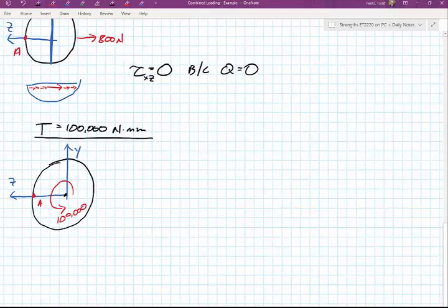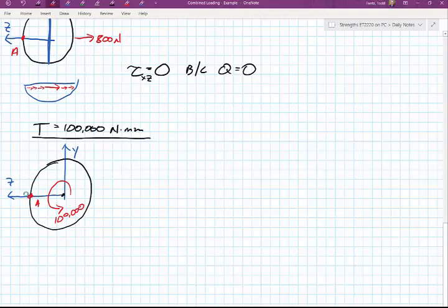So what would happen to my shear stress is, anytime you have a torque, it basically pinwheels around. The easy way to think of it, it's tangent to the surface. So this is my shearing stress. If I wanted to put a subscript on it, I'm still on the x face because the x is perpendicular to the surface, and then it's pointed in the y direction.